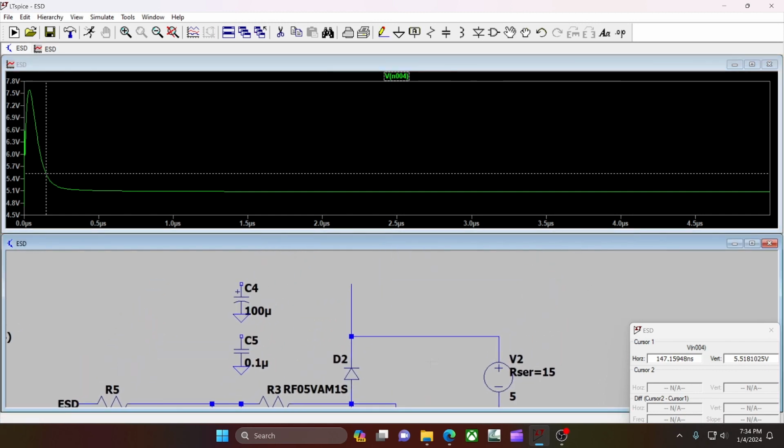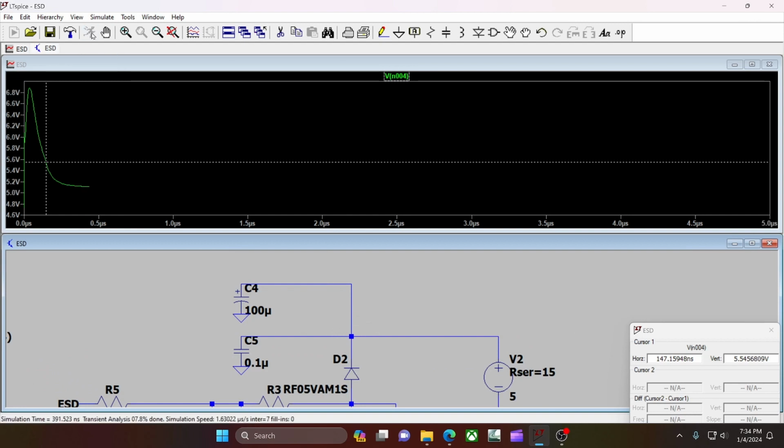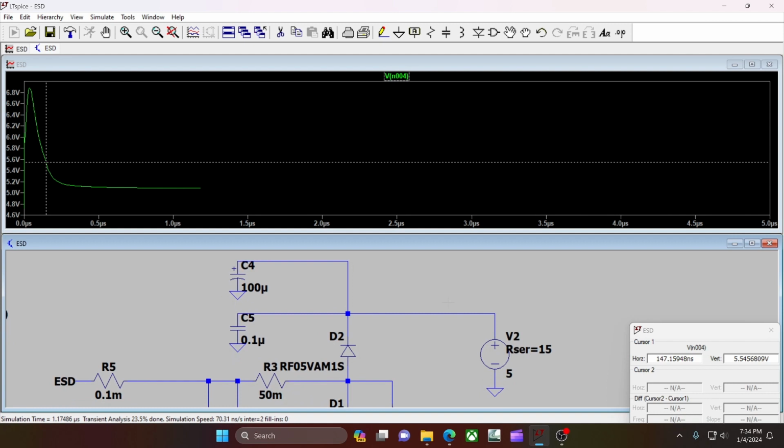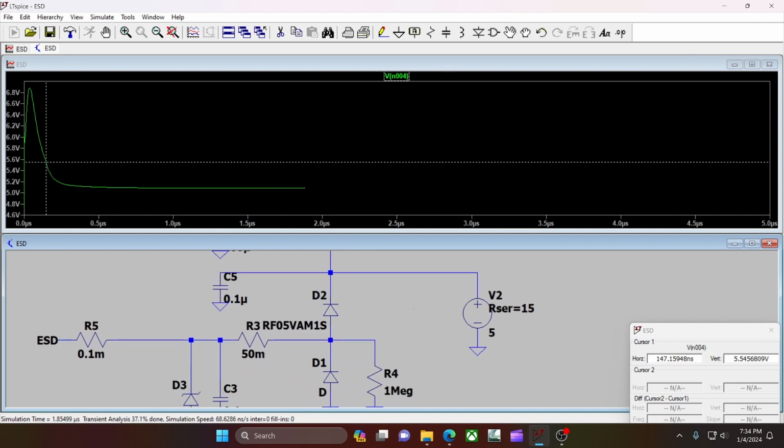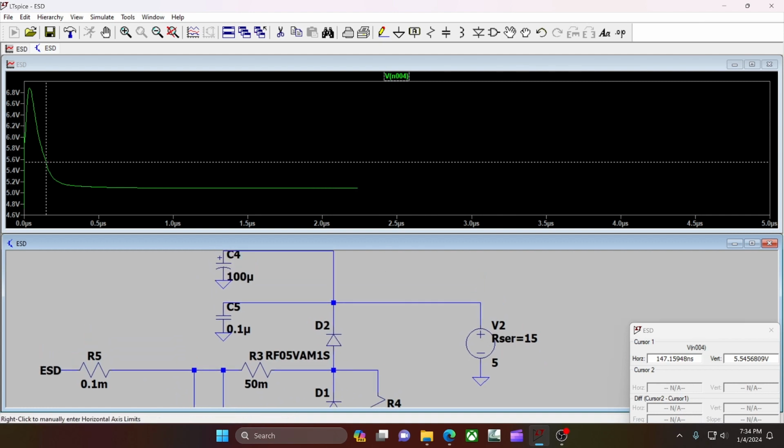Okay, now what we want to do, let's bring back our bulk caps. Or bulk and decoupling cap. Let's run that. 6.8. Oh, and now it's going forever because I have the inductance in here. Boo! So yeah, when I was running through this by myself, I was having this weirdo stuff happen, or sometimes where it would just break.